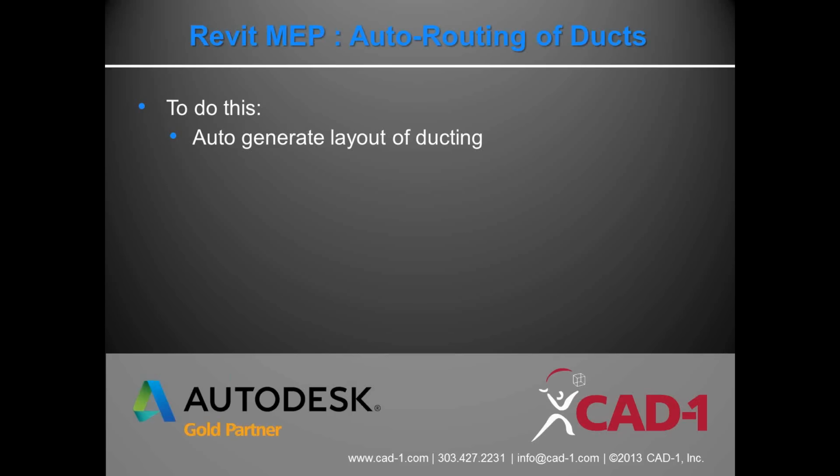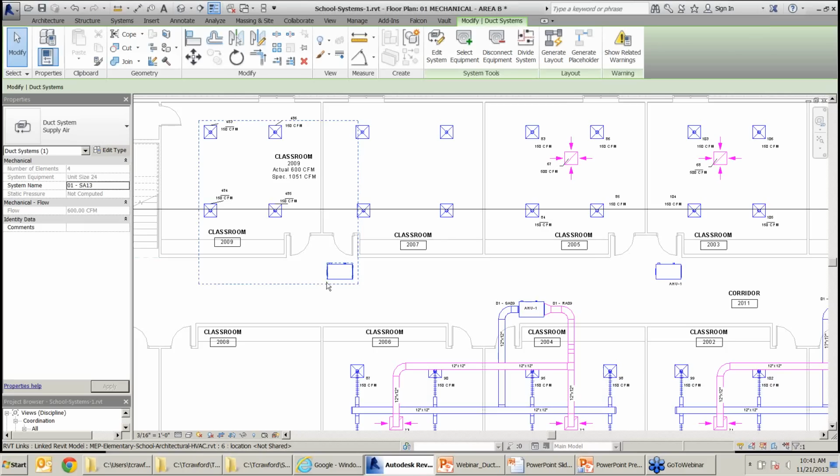So I added a few other things. To do the auto routing of the duct, I need to have duct systems. Well, we just created those, so let's go back to Revit and take a look. I have my duct system. I have it selected. And if you remember, it's context sensitive, so anything to the right is specific to whatever I have selected. In this case, now I have the option to generate a layout.